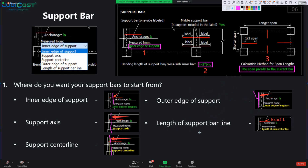Length of support bar line, right? Or the exact length that you key in inside here without the anchorage LA. Exact length is without the anchorage LA. So it depends on which one you feel like using. But usually we don't change this. We always put as inner edge of support plus the anchorage LA. If you don't want the anchorage LA, then you just put length of support bar line.